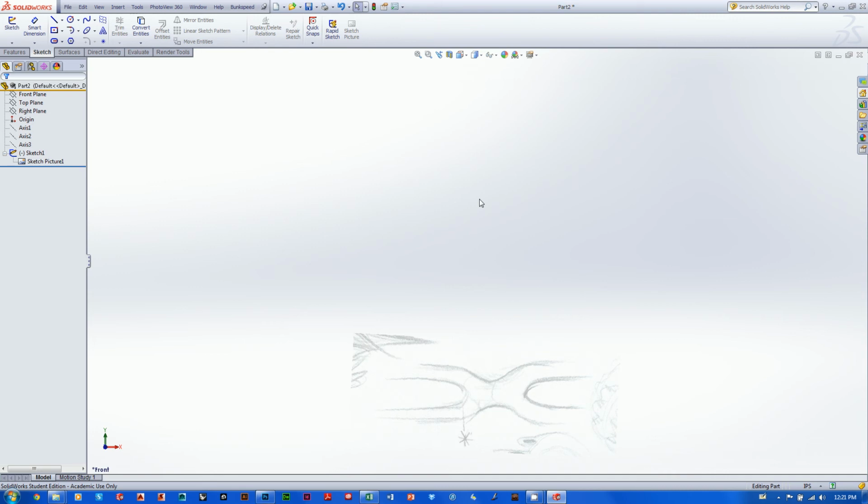And I'm talking about millimeters now, and so I want to switch my document to millimeters. Down here in the lower right-hand corner, there's this IPS button right here, and if you hover over it, it flashes, it says inch, pound, second. Open that up, and you can just go ahead and switch it to millimeters, and now all of your units will be switched to millimeters. Okay, good. So, like I was saying, I want to make a bracelet that's going to be 12 millimeters wide.